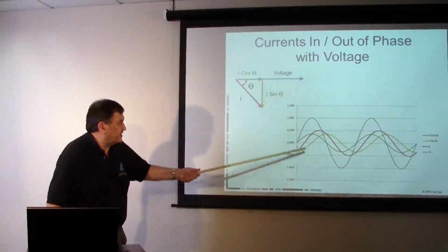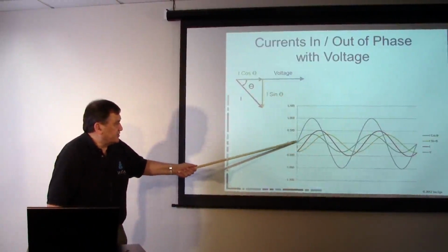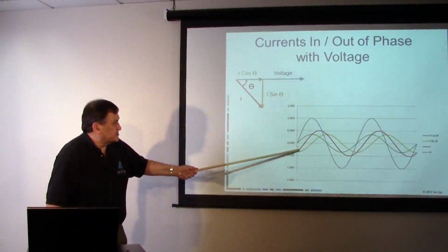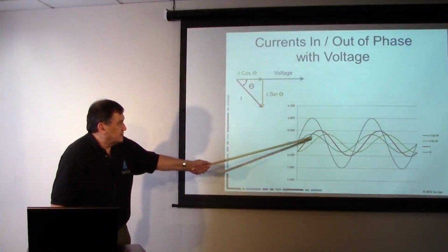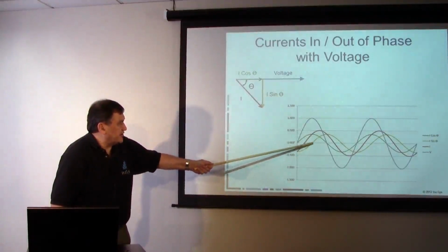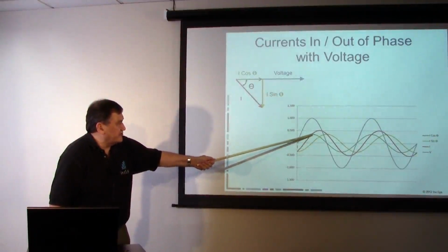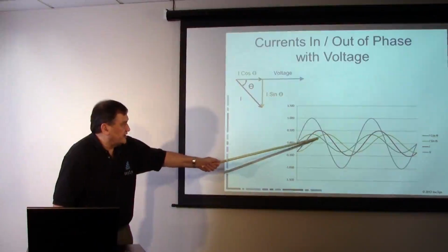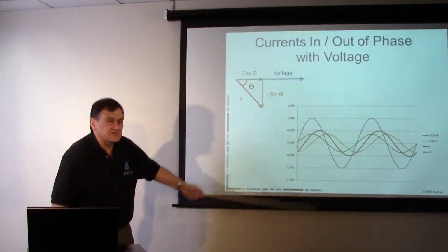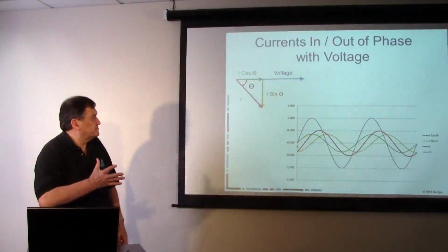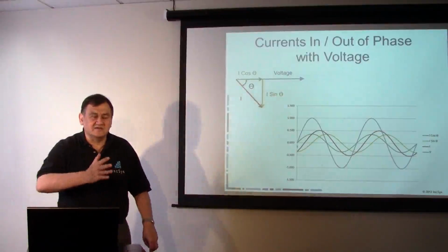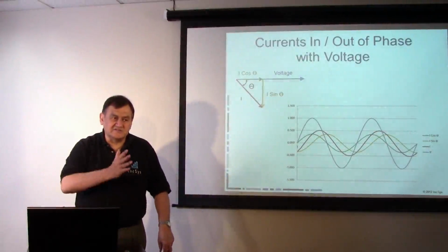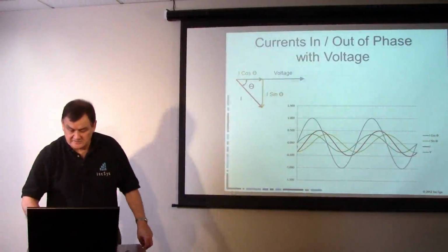And you can verify that, okay? At this point, green is 0, so my red is just the orange. At this point, my green is peaked, my orange is 0, and so our green is equal to the red at this point. And at this point, we're summing these two values to get that. So just take it on faith that we can break a sinusoidal waveform down into two orthogonal components, 90 degrees separated from each other.